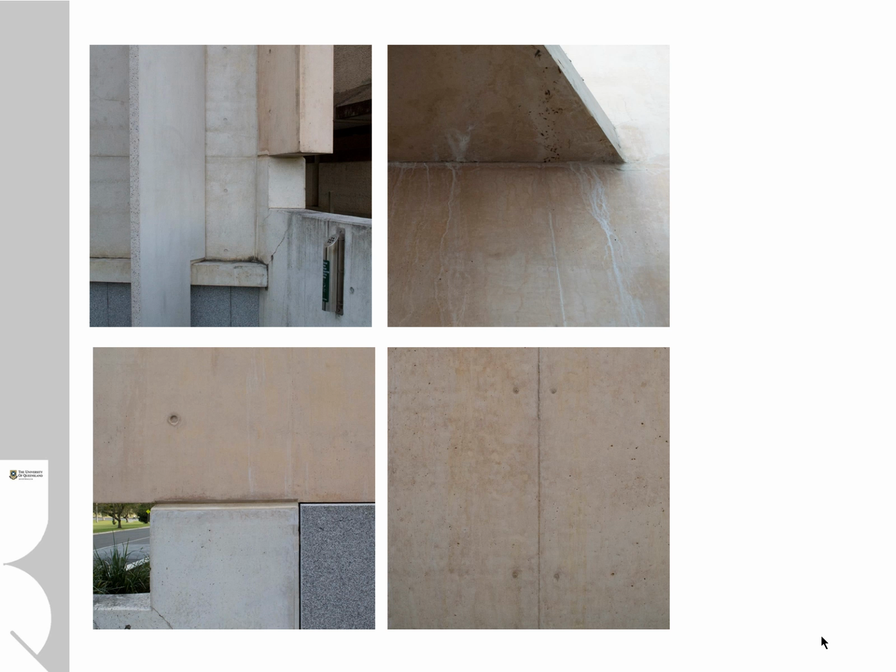You can also see in the bottom right hand corner, again, although a very high quality finish specified, there's a lot of imperfection in that, a lot of blowholes on the outside, and the colour consistency of that wall is not brilliant. So although you can specify the highest, concrete as a material is reasonably unforgiving and hard to work with to get absolute perfection. And perhaps the thing is just to simply accept that and to design with it.